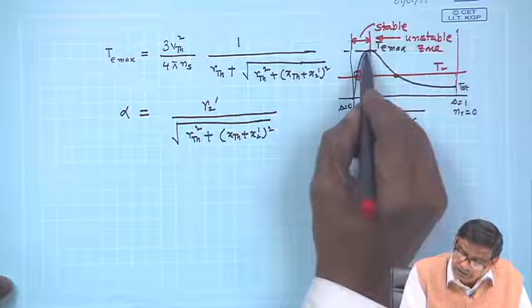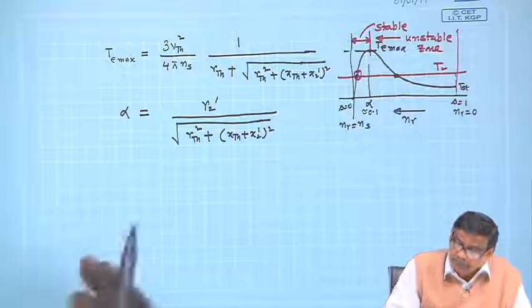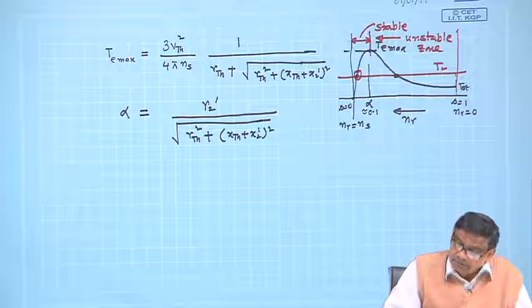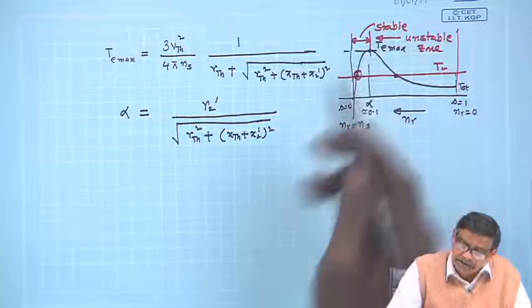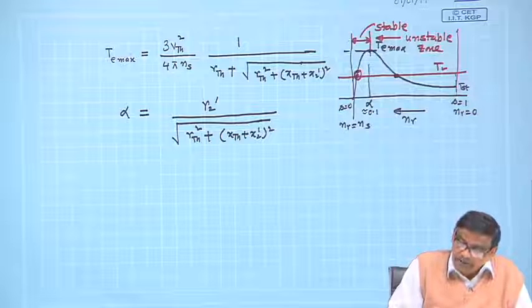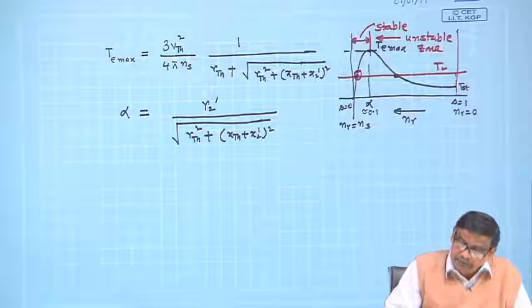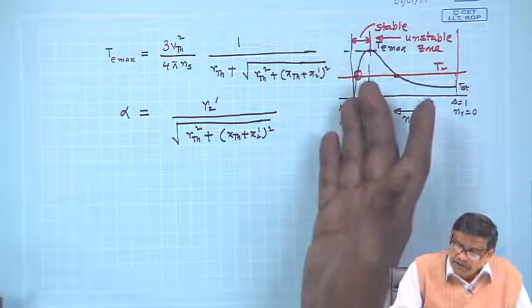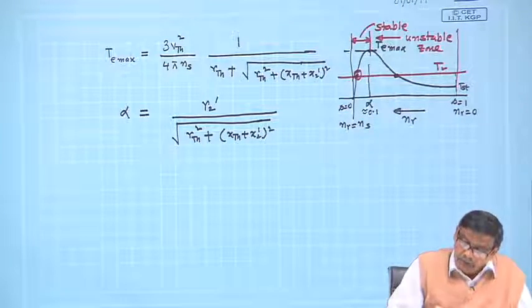And the motor will operate primarily in this steep portion of the torque slip characteristics. And also we noted that the full load torque will be more or less in between, so that you keep enough margin from the line of demarcation between stable and unstable zone, and the full load slip could be of the order of 0.05, half of this is 0.05 and so on.